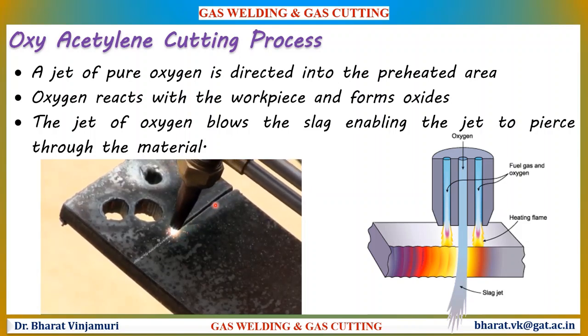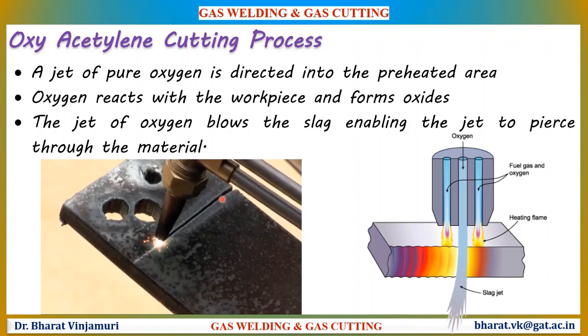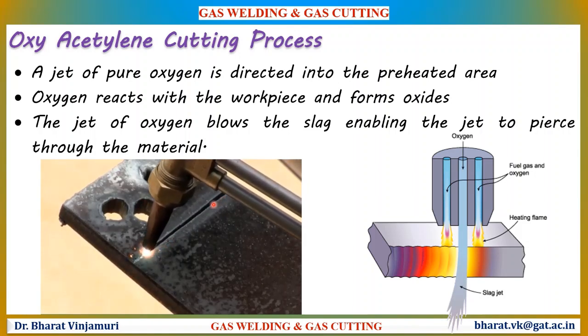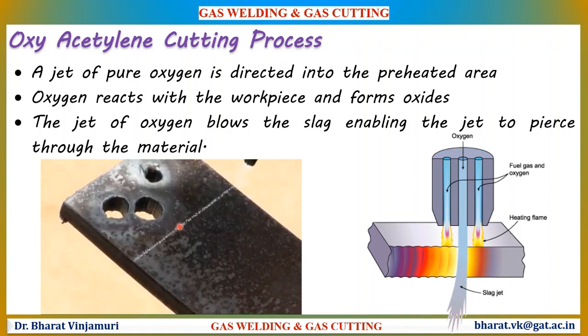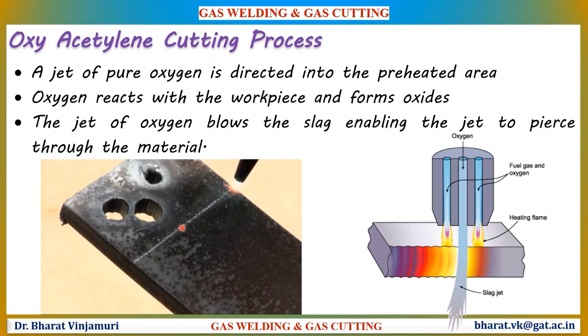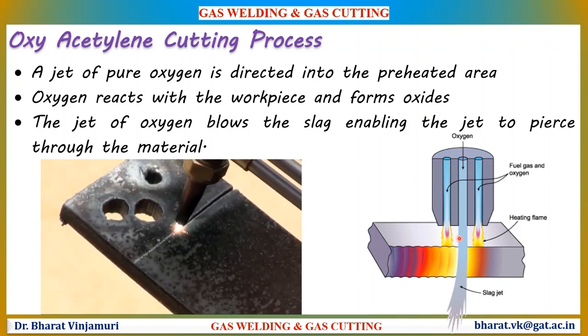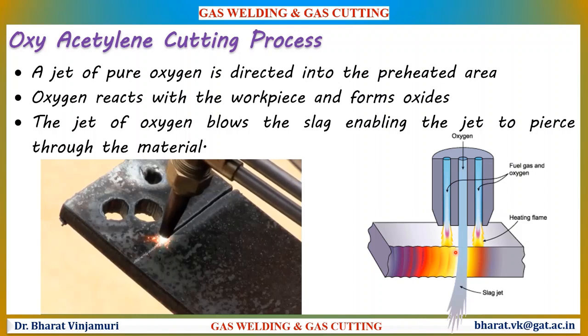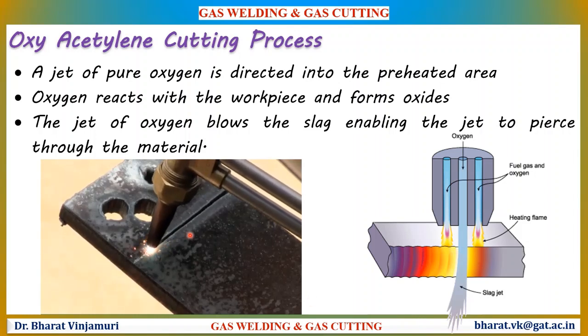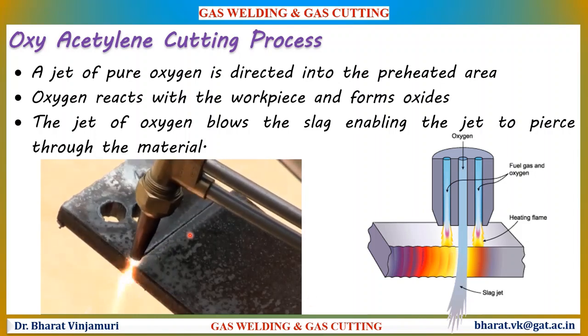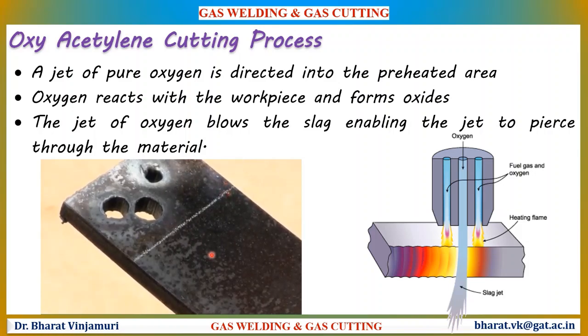When the workpiece is cut through a thermal cutting process, the width of the cut is referred to as kerf, which depends on the oxygen hole size in the nozzle tip, the flow rate of oxygen through the central hole, and the flow rate of preheating gases. Also, the kerf depends on the speed of cutting and the nature of material being cut.